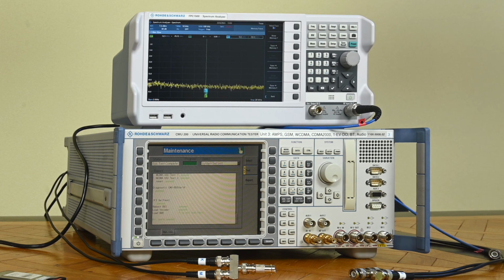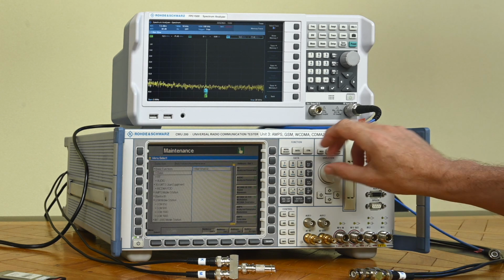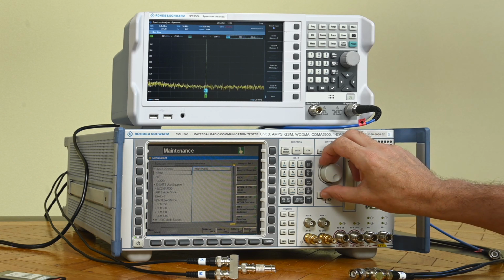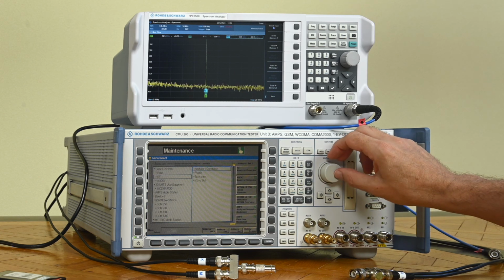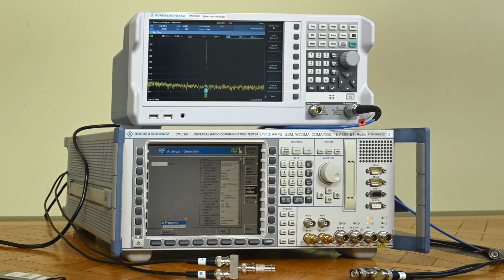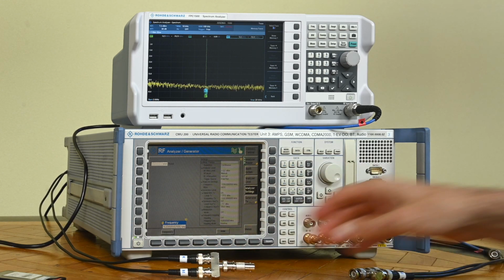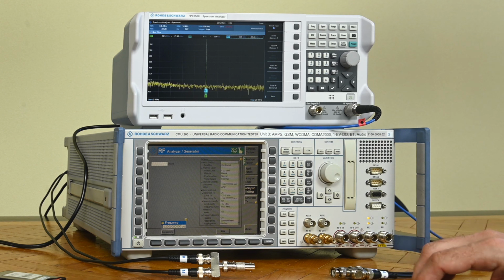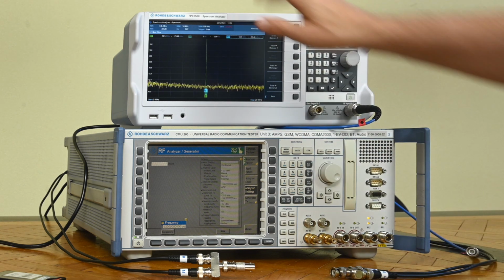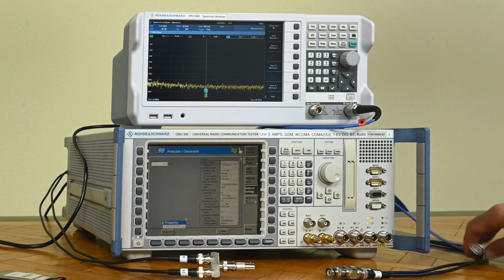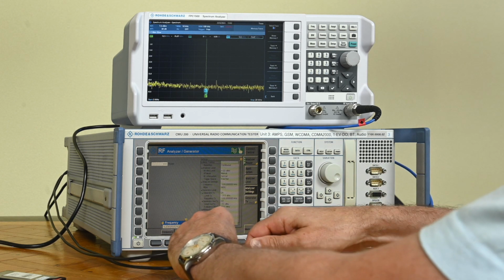I would like to continue now to do a couple of tests on the IF path, to see if it is properly working. So to do that, I'll just put the device in RF mode, and we can go to the generator analyzer function. What I actually did, on the new IF connectors on the back of the device, is make a loop over here. This is the transmit path on the left, and it's the receive path on the right. And I would like to see if we first actually get to see these signals. So let's first see on the transmit path if we see anything.